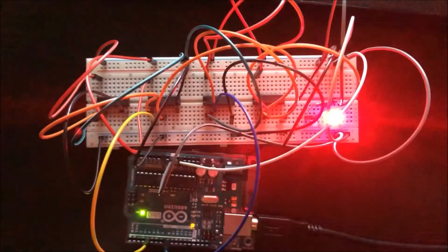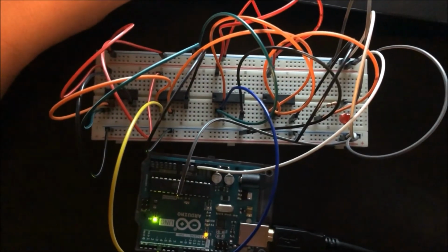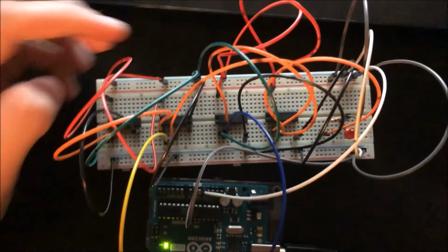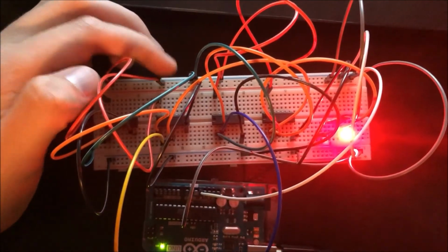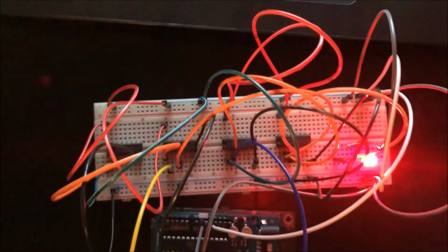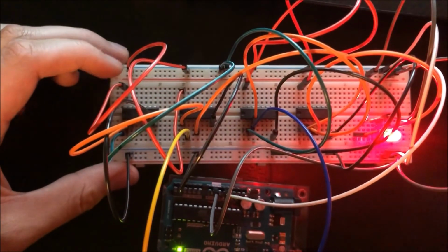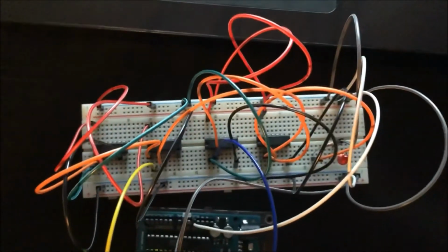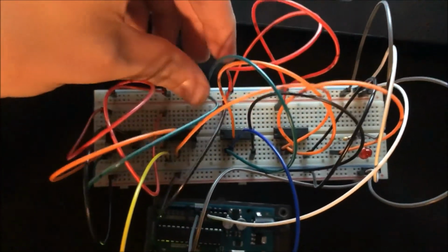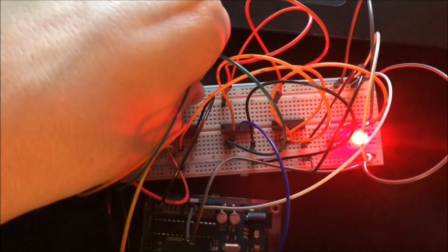So for the final part of this lab experiment, I connected inputs A and B to Arduino inputs, and in the Arduino code, I made it so that when the selector is in the high position or the low position, the LED flash will change accordingly. The reason is this is a fundamental part of a 2x1 multiplexer where, as it is currently, the selector, these green wires right here, are high, which means B is the predominant one passing through, and the frequency is 0.5 hertz. If I were to make these low, we would make A dominant. A has a frequency of 10 hertz.